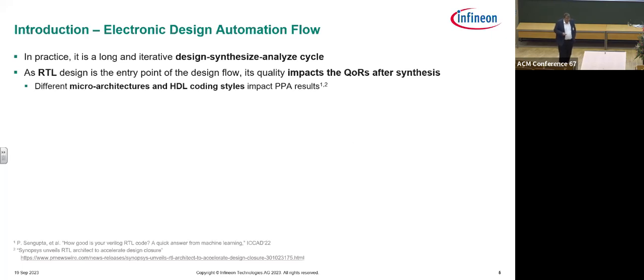And still today, the synthesis result is heavily coding style dependent. This is unfortunate, but easily, if you make an experiment, a CPU, ALU, make a hand optimization, you get 20, 30% optimized area over standard commercial synthesis tools, which is still amazing.